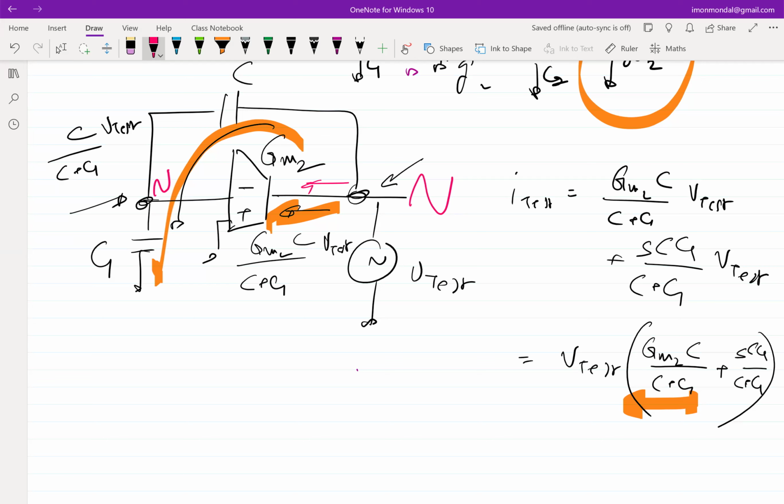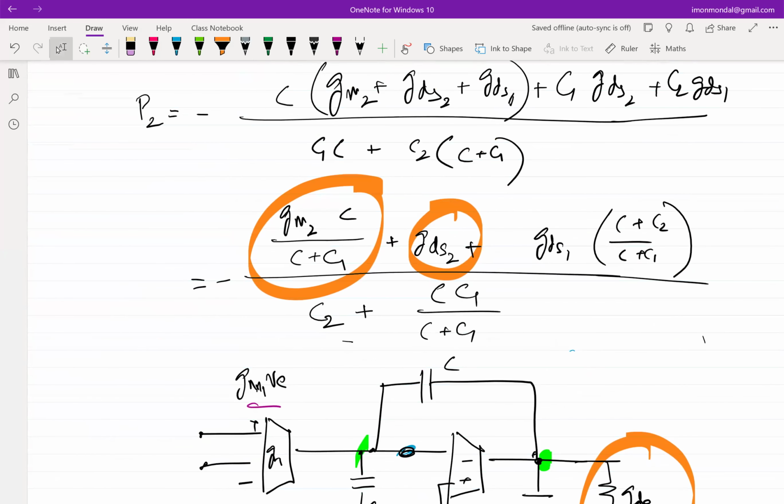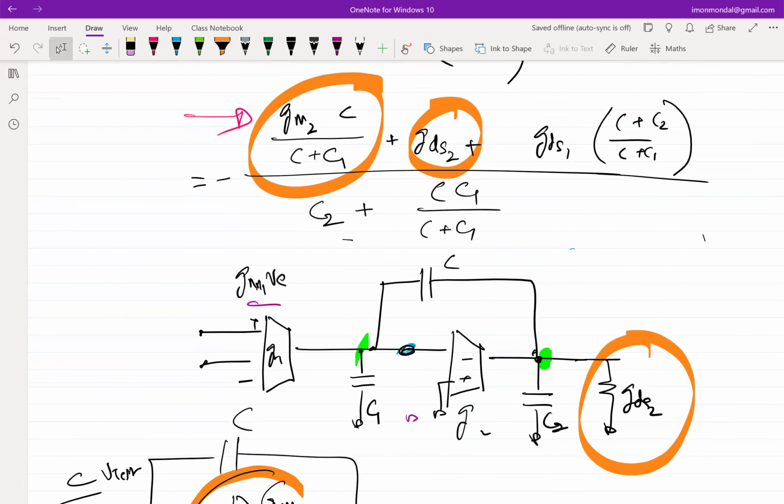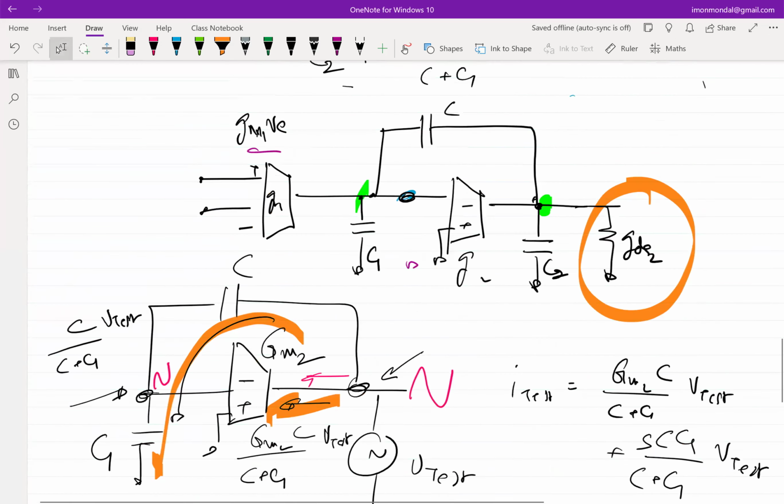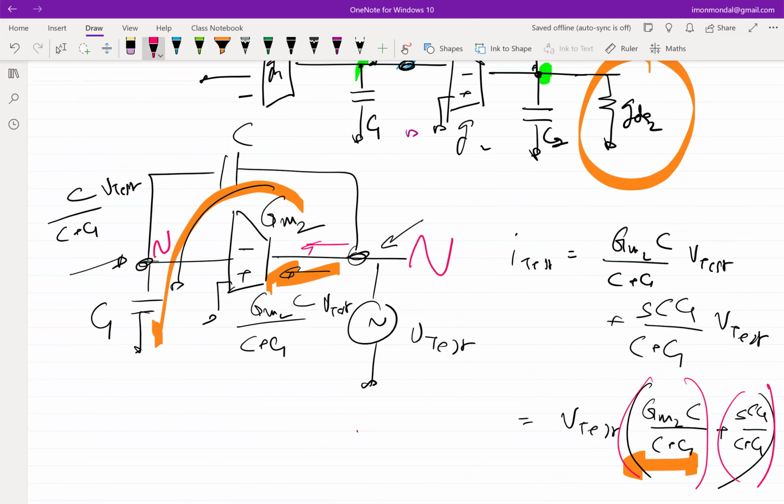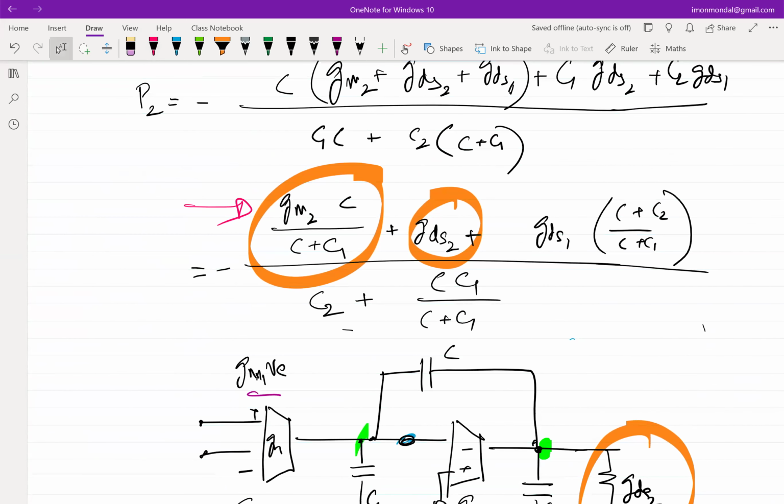You are getting a resistive current and you are getting this capacitive current because the capacitance is already attached to it, right? So the key thing to note here is that the effective conductance at the output node has gone up because you are drawing a resistive current in. And the effective capacitance has gone up by this exact same amount, which is equivalent to the one that you are getting due to feedback. Okay. So essentially, now if you look at the top terms, the dominant term will effectively become this, and the capacitance will effectively become this.